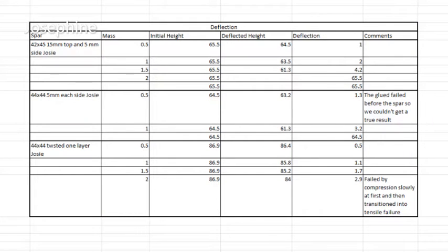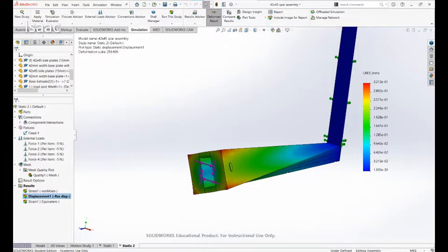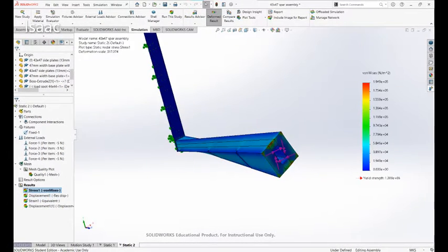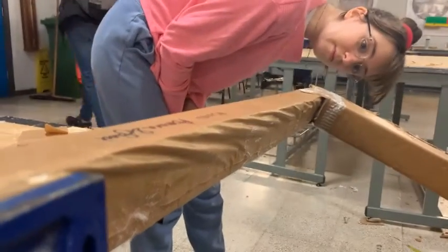Torsion occurs due to unequal load distribution at half chord point. The wing must have torsional compliance to be capable of flight, which here is 3 degrees. Loose joints, as seen here, cause extreme twisting, but not suitable for flight, and a folded spar design prevents this.